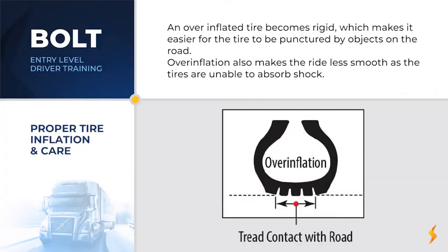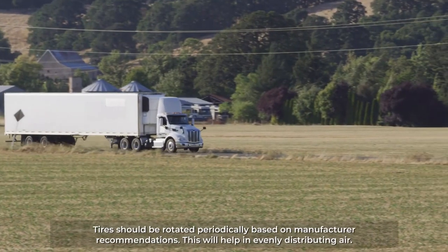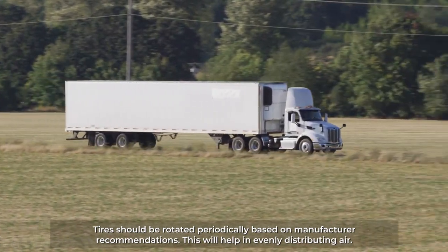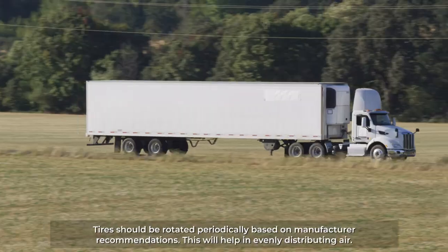An overinflated tire becomes rigid, making it easier for the tire to be cut or punctured by objects on the road. Overinflation also makes the ride less smooth, as the tires are unable to absorb shock. Tires should be rotated periodically based on manufacturer recommendations. This will help in evenly distributing wear.